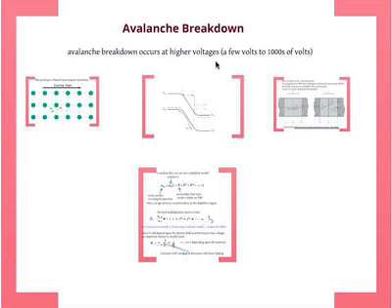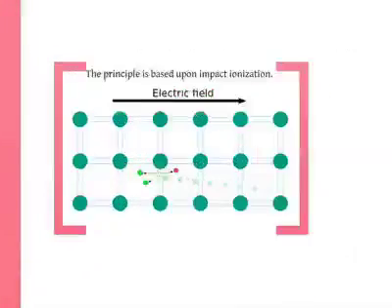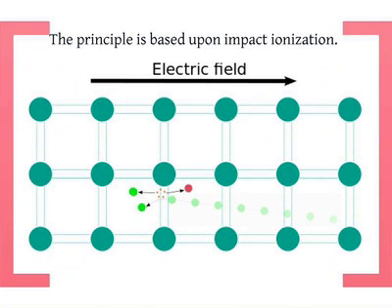Okay, so you have P plus N or N plus P, which has to do with the fabrication. You start with the N-type silicon wafer and you very heavily dope it to make it P+, so you get the P+ N junction. For practical reasons, many of the diodes that you can buy which are in breakdown turn out to be avalanche breakdown. But in any case, Zener breakdown is also important because of the lower voltages required.